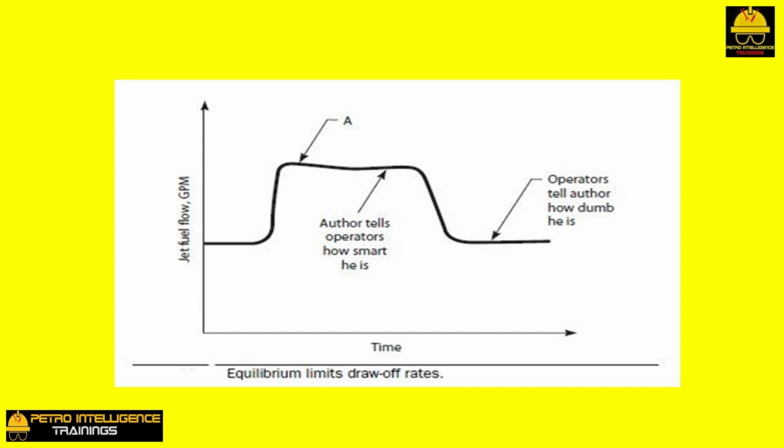But the sump was only 4 feet high, and he needed to increase jet fuel flow even further. So, he raised the pressure in the crude column from 10 to 14 psi. This increased the pressure in the draw-off sump by 4 psi. The results of this increase in pressure are shown in picture. At first, the increase in pressure greatly increased the flow of jet fuel. But after a few minutes, jet fuel flow slipped back to its original rate.